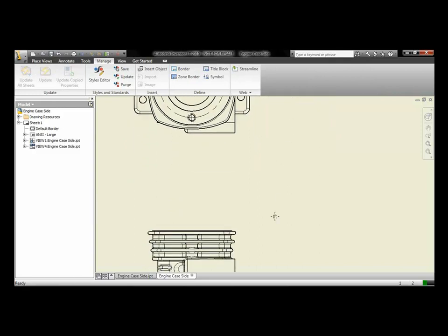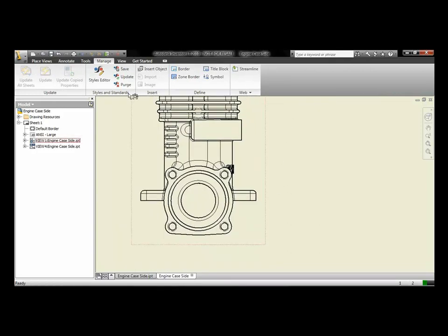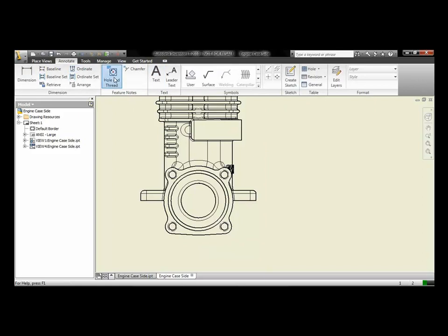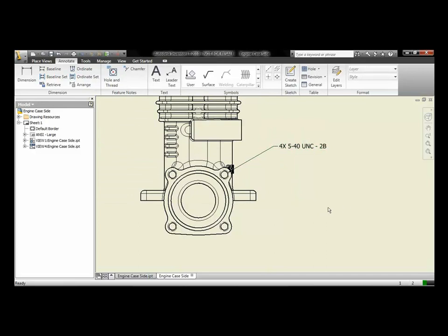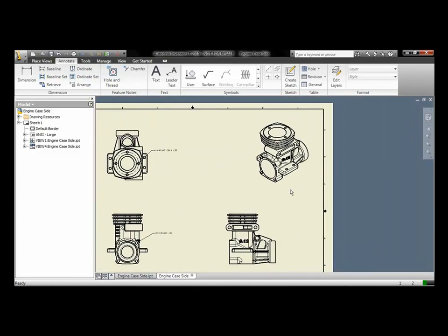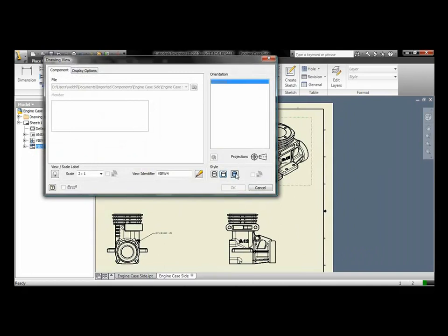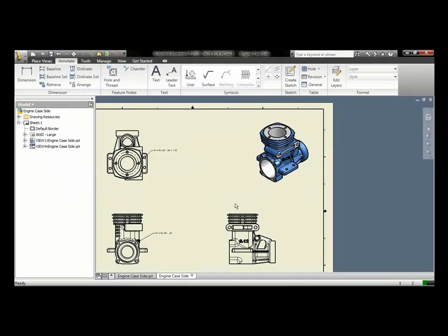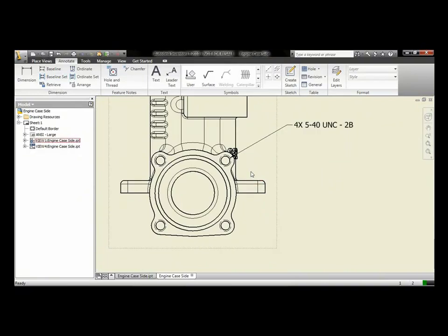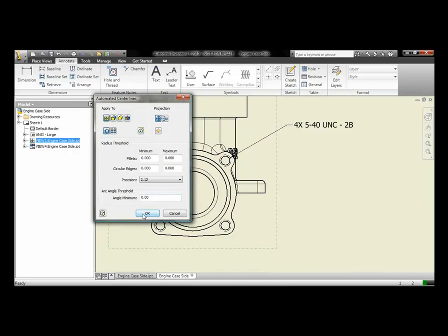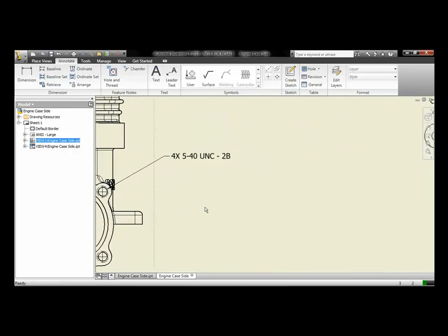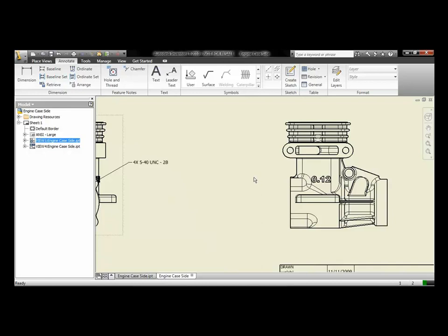So now we're documenting these tapped holes that we put on our imported model, so we can actually manufacture or machine these particular geometries. And again, we could add any additional dimensions that we wanted inside of this Drawing Manager. For sake of time, I'll just place a few on here. And again, I just like to show off some of the complex views we can create, like a color isometric view. That again, an isometric view in general probably won't be done inside of a 2D design environment, but it's certainly not a color one. So let me finish making some center marks, and then let's maybe add a couple dimensions.